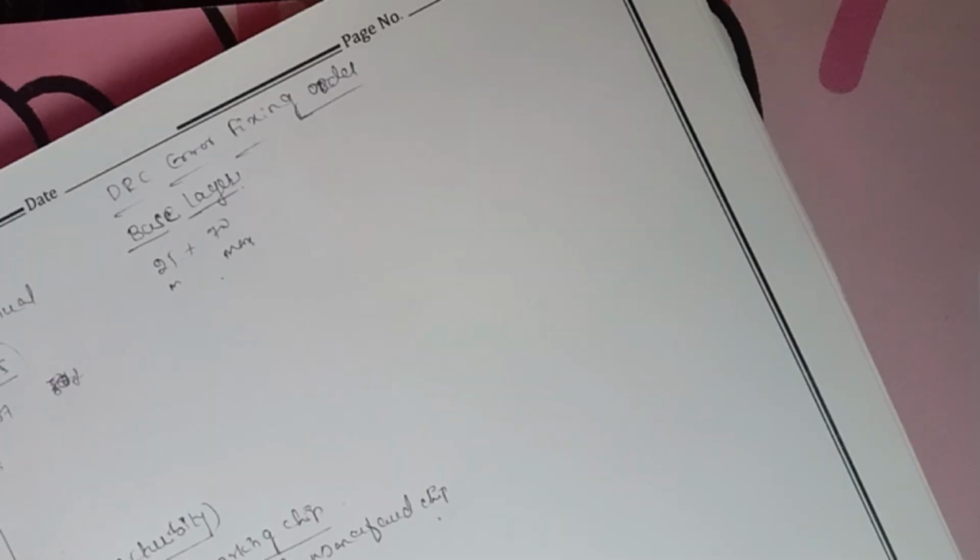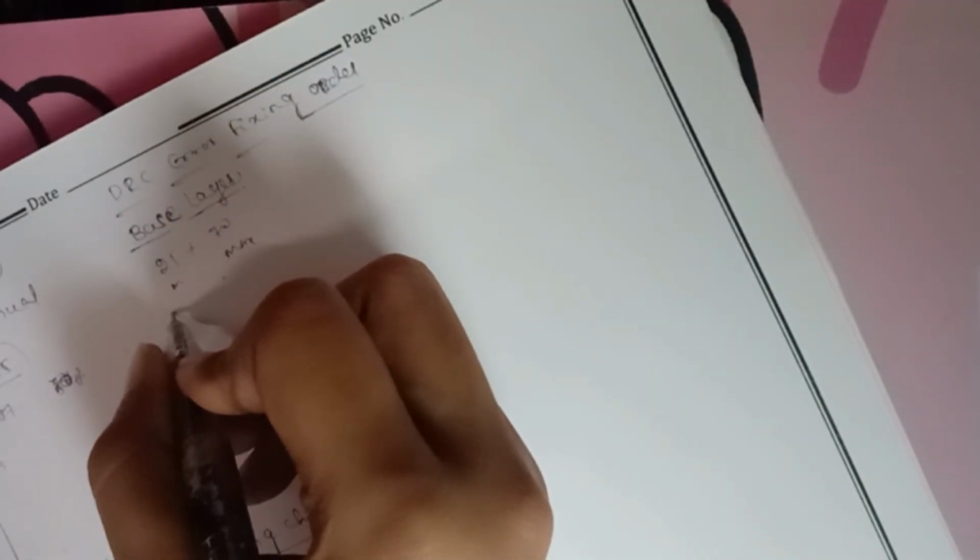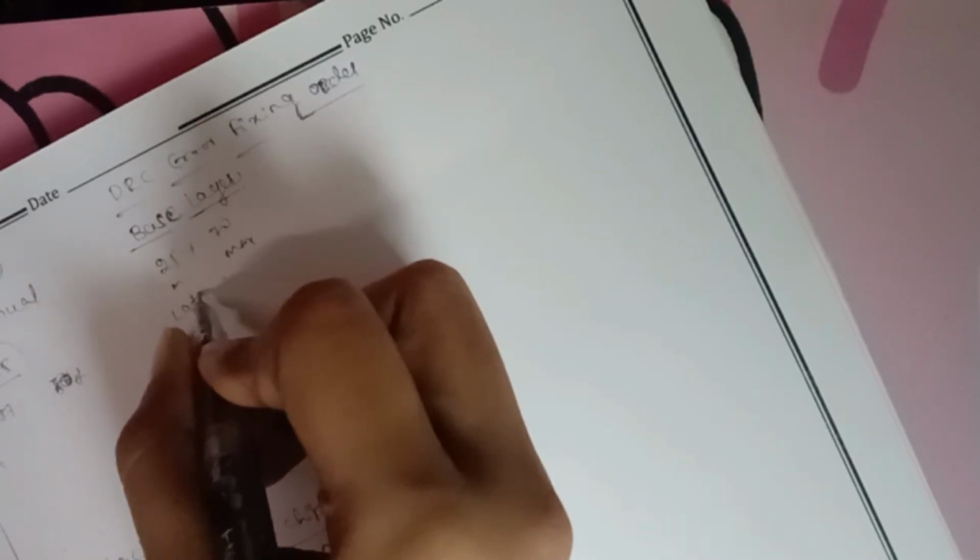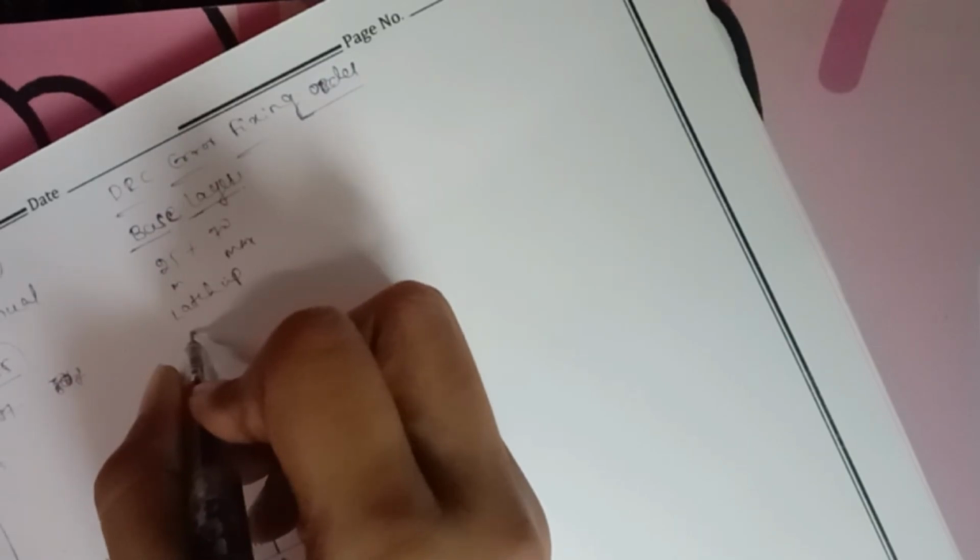Next, latch up, NVL, NP, these are the base layers. These should have correct spacing with the correct width, space, and all the things. It should be managed correctly. These are about base layers. Which are those? Latch up means adding the tap cell or connection of the body, NVL, then NP, PP, poly, OD. Okay, these are the base layers.